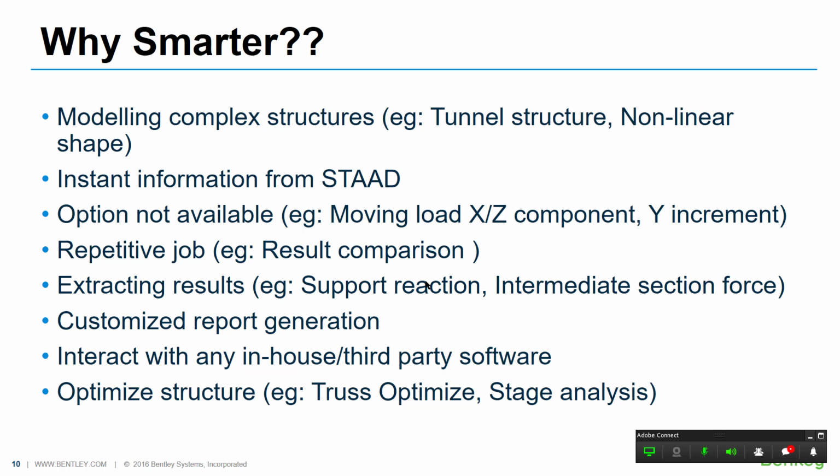And yeah, interaction with any third party software. If you have some program that you have written for foundation design or deep beam design or any specific type of member design, probably for steel structure you have some cruciform section, and that cannot be designed at this moment using STAAD. You have written some in-house program which can handle this particular situation, but you need the member forces or the support reactions. So you need to get that particular information from the STAAD window to run your in-house program. That can be done using this particular OpenSTAAD function.